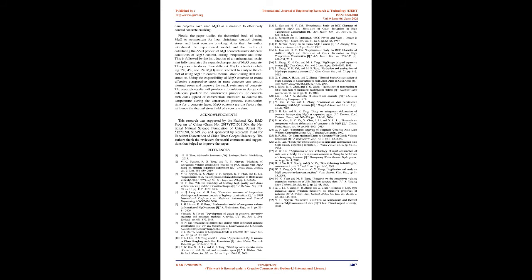The calculation results in Fig. 4 to Fig. 7 show that the maximum tensile stress of all points in the dam satisfies the permissible stress conditions. When 5% MgO is added, the concrete can obtain the most effective tensile stress. The results show that, moreover, to meeting the premise of stability and economic conditions, concrete with a higher MgO content will have a better impact on the stress state of the dam.